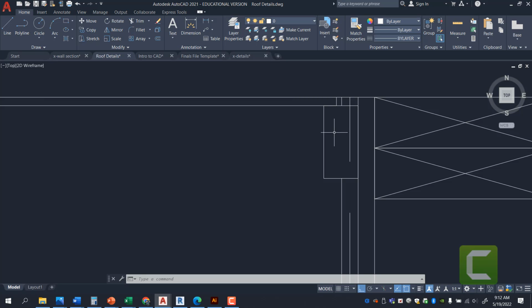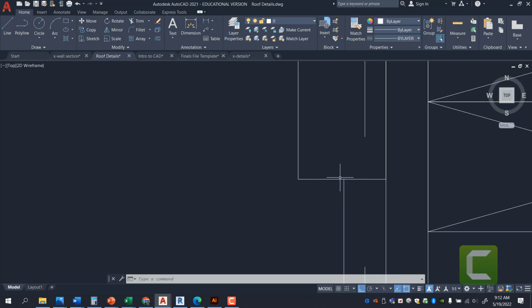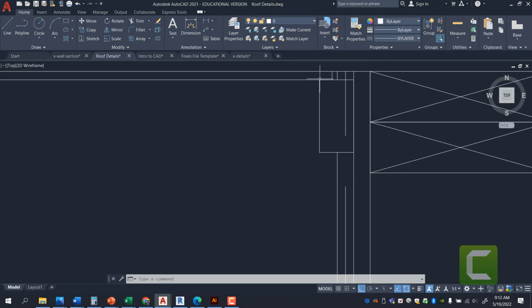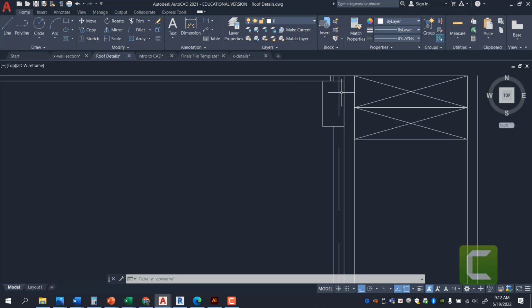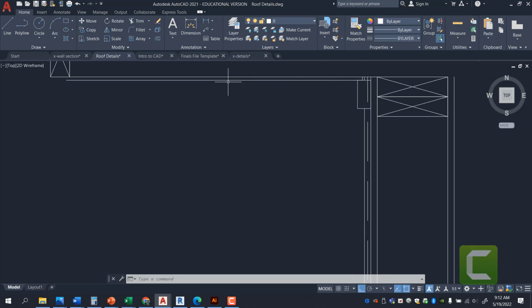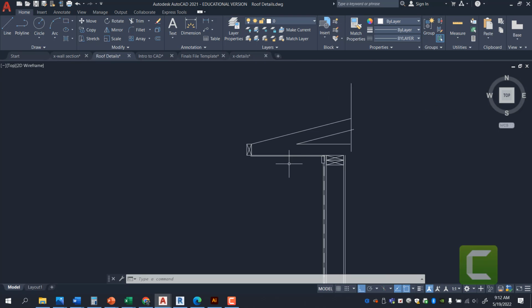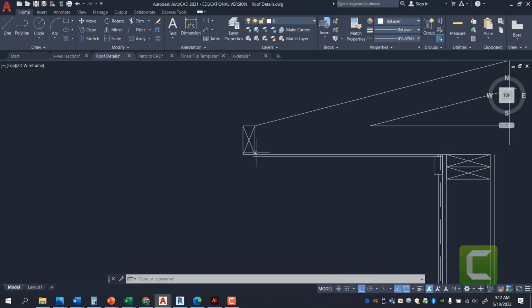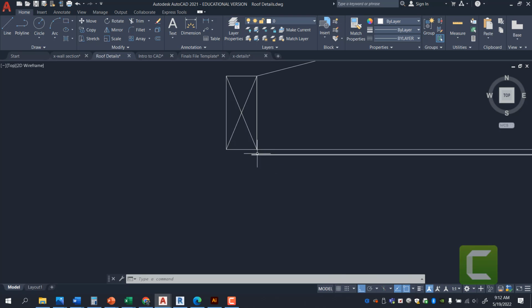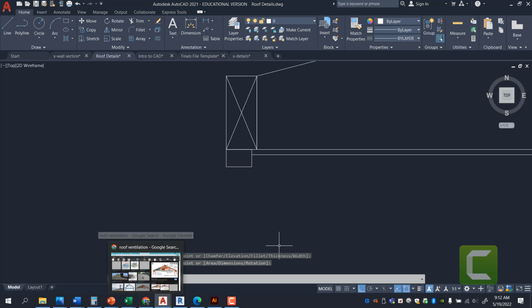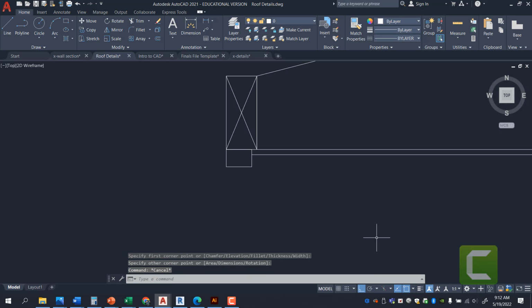It creates a much cleaner detail, and at the same time, it is easier to caulk this corner and caulk this corner right here, or this edge, knowing full well that your soffit is well covered. So this is how I like to do my trims, and this is something that is particular in my taste. Same thing here. I would rather have my soffit die sooner and put my trim right around here. I'd rather do that. Now, these trims can be straight off of Hardy website.